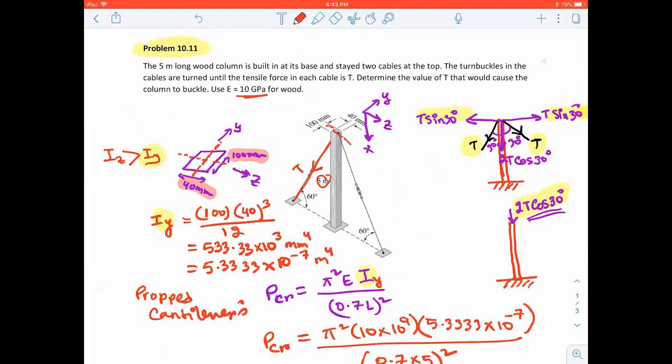But if you were to have any problem where you do not have any restraint, say if you have pinned or pinned-fixed column, then you have to consider in which direction the moment of inertia is lowest.